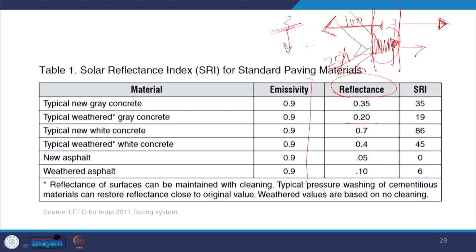So, it will be re-radiating or emitting this heat which is absorbed. What we are looking for here is to emit all that heat which is absorbed. If that happens, and we are able to reduce the amount of heat transferred inside by providing some sort of insulation or barrier, most of the absorbed heat will be re-radiated, and less heat will be transferred inside.